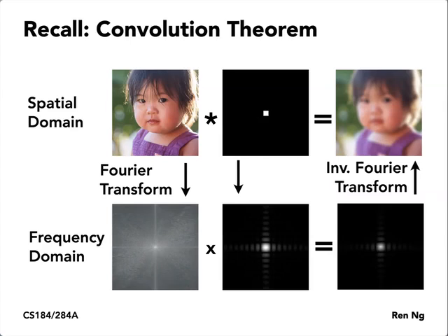The convolution theorem says, though, that you could take exactly this mathematical operation that you want to implement in the top line, and you could implement it in the bottom line in terms of its spatial frequencies. So in the Fourier domain, specifically, you compute the Fourier transform of the input image, and you compute the Fourier transform of the filter kernel, then you can get the Fourier transform of the output image, this convolved image, by just taking a pixel by pixel multiplication of these two.